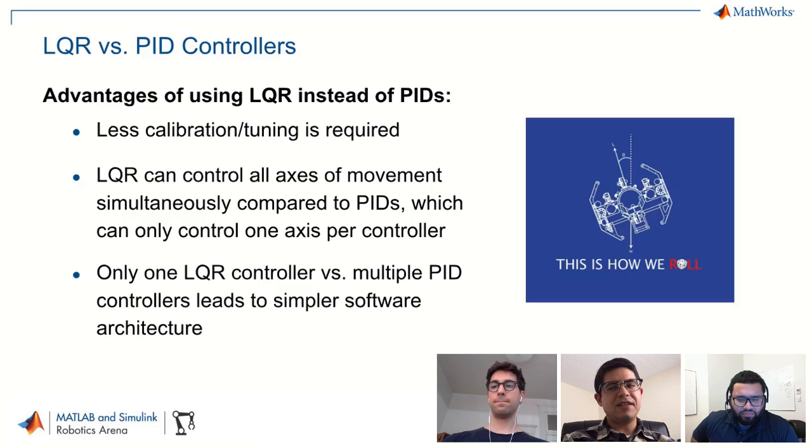And so it just became really unfeasible to keep calibrating the PIDs. And so with an LQR controller, because the physics are already kind of implemented into the controller, it actually allows for a lot less intensive calibration. So there is some calibration that's required, but right now it takes us at most half an hour if we want to do a very thorough job.